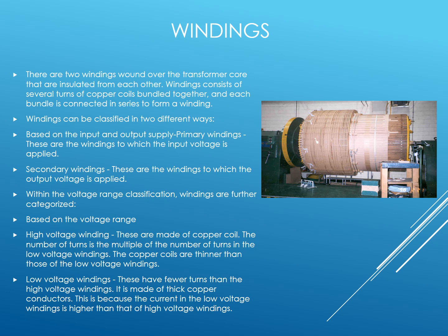All the parts are insulated from each other by paper. That is, paper acts as insulator between the low voltage and high voltage windings. Top and bottom coils are always low voltage windings for proper insulation.